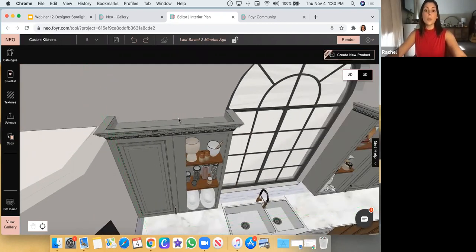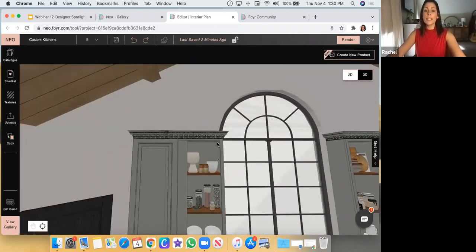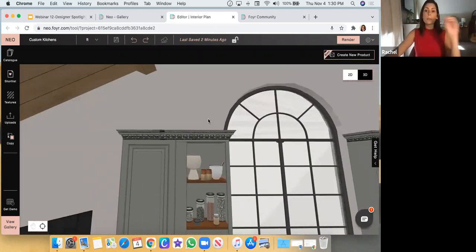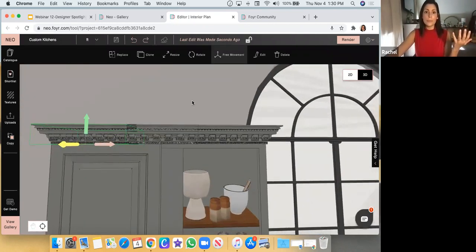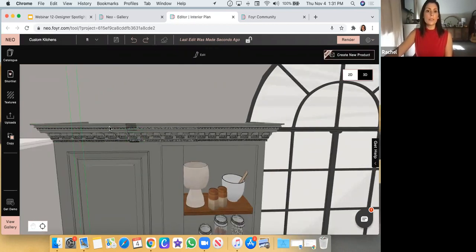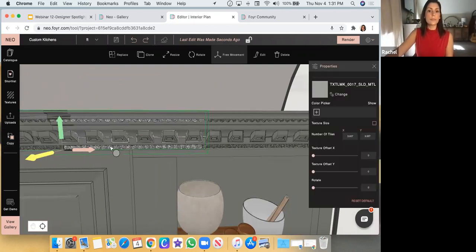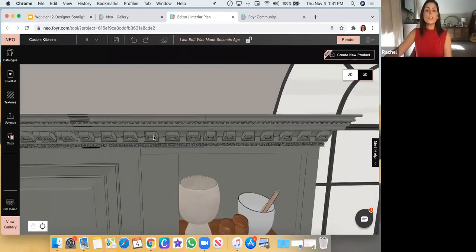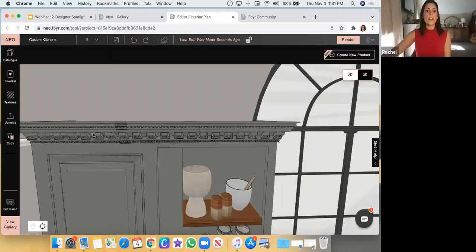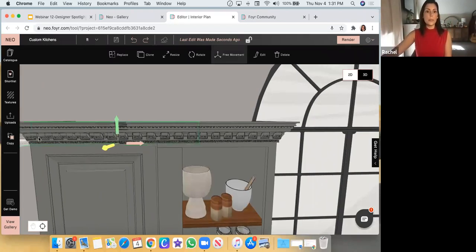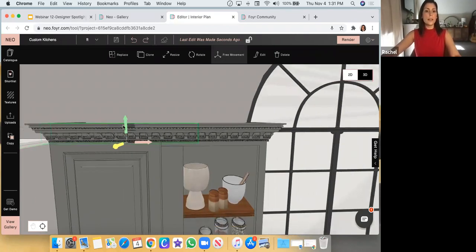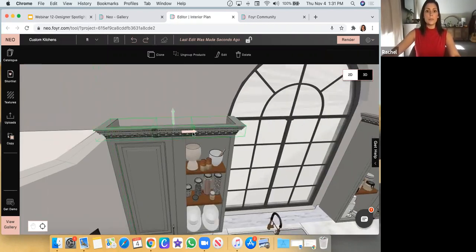So the last thing that you can do, say you had something very similar here, or you're just worried about these moving independently, is group them so that if you do accidentally grab it and move it, you're not in a situation where you're moving a singular piece. Oh, I'm going to apply the gray. So these guys too, okay. So I think these are already all in free movement. I'm going to hold down Command Shift for my Mac, click on all 3, group them. And now I can move them jointly.